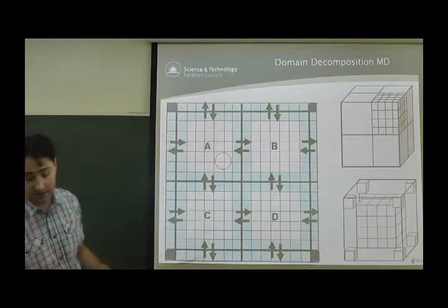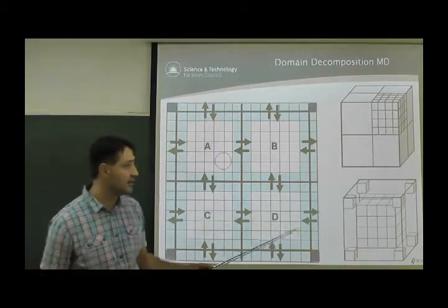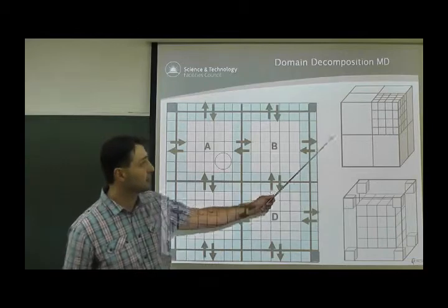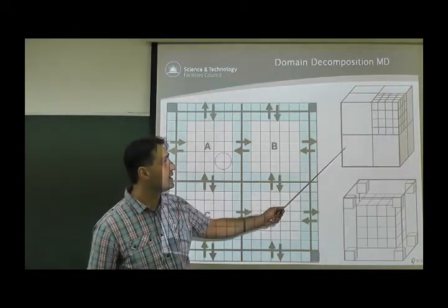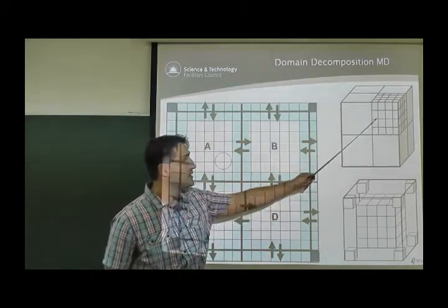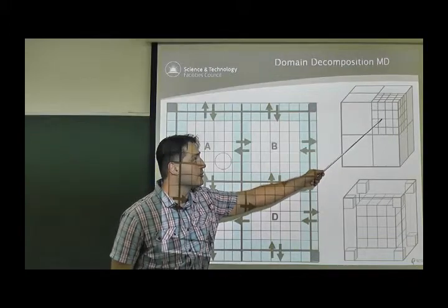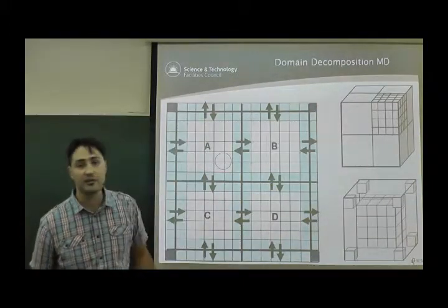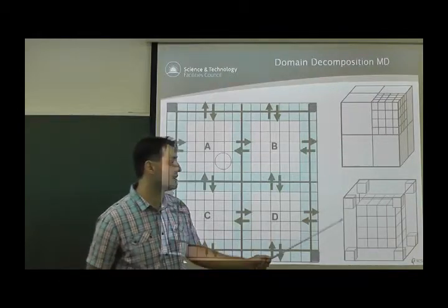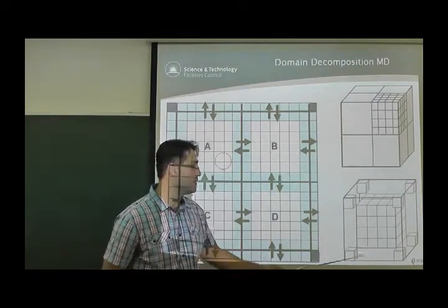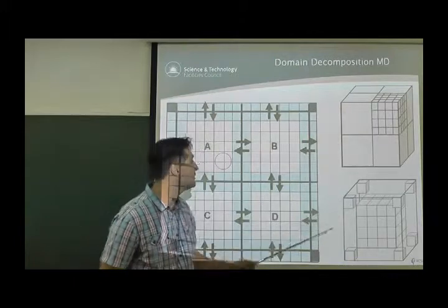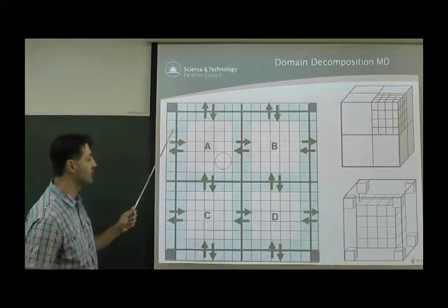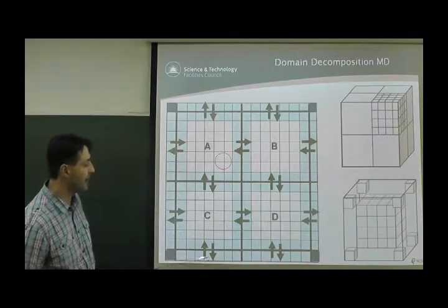If we're in 3D space, then we can see what it looks like now. Our system has 8 processors, and this is the finer mesh of what we call link cells. In order to have the system contiguous and all processors to know everything about everything, we need to send something that is called halo, and here this is demonstrated by the blue bands around.